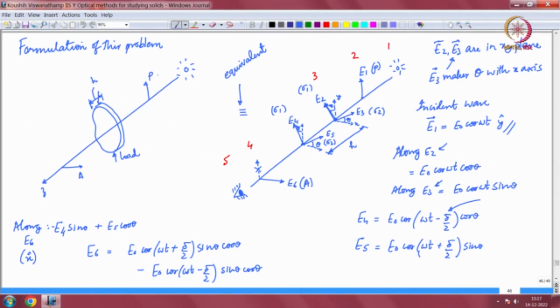So, remember that if there is no stress, or if the material is not birefringent at all, then you will not see anything. This will only allow polarized light in this direction, the electric field vector is like this, and this will only allow field vector like this, right. And since they are perpendicular, if you do not have any stress field at all whatsoever, then you will completely get a black image, right. So, this is referred to commonly as a dark field. We will talk about this in more detail today, and this is what you are going to pick up, right.